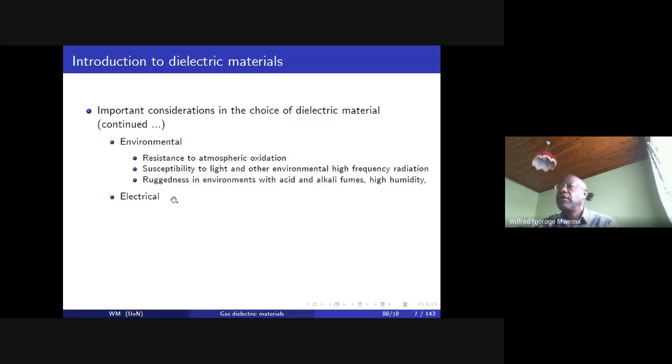They could also be electrical, where the electric strength is the most important, the dielectric constant and the loss tangent, because, for example, in an electronic circuit, especially in the area of miniaturization, the wavelength or the velocity of the wave propagating in these materials will decrease with the increasing dielectric constant, because we have seen that the phase velocity of light is proportional to 1 over root epsilon, that is, the electric permittivity of the dielectric.